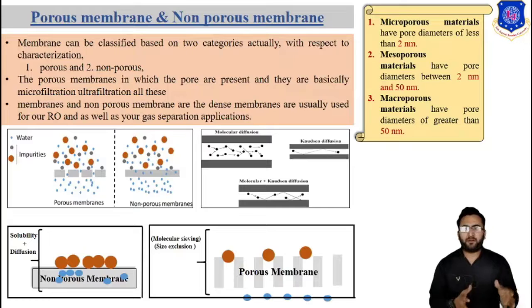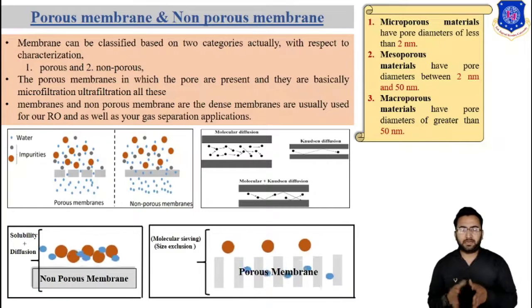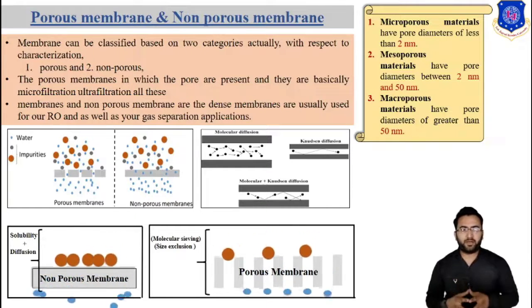With a membrane of this type, it is not the membrane material we are going to characterize, but the pores in the membrane. So when talking about porous membrane characterization, please note that we are characterizing the pores. The membrane material has nothing to do with it. The pore size and the pore size distribution mainly determine which particles or molecules are rejected and which will pass through the membrane. Let us now discuss a little more about porous and non-porous membranes and how their mechanisms actually work.